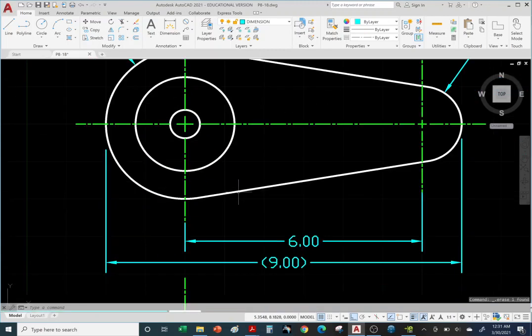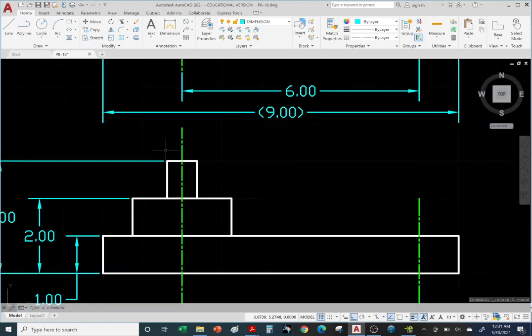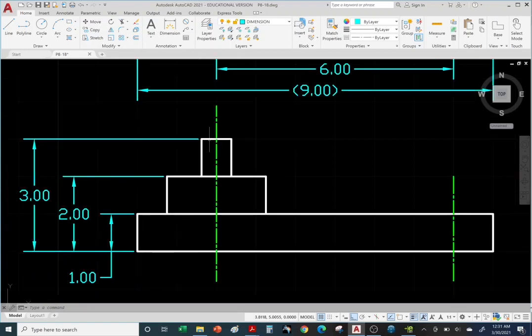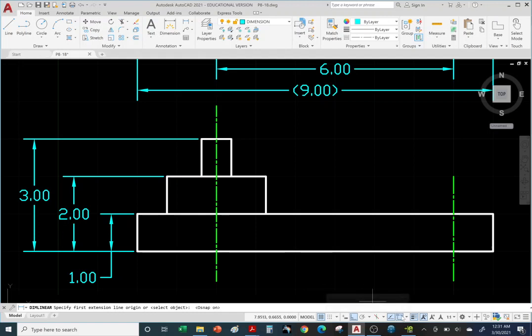Instead, you have to dimension the rectangular view. So these are round shafts, but from this perspective, it looks rectangular. So you actually have to dimension these with the diameter, because these are solid shafts and not circular holes. Okay, so we need to throw in linear dimensions. Let me turn on object snap.